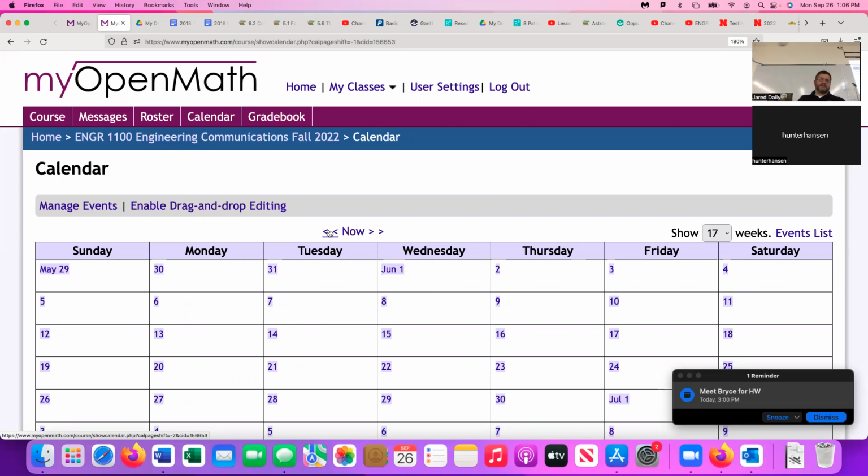That's a little too specific, because the pattern that you use to lay out your rebar is going to be determined by design things that you haven't done yet. You have to first design the bridge before you decide on a pattern to lay out your rebar in. You also wouldn't necessarily put in laying or surfacing the bridge with asphalt, because you may not end up surfacing with asphalt in your design. In the process of designing the bridge, you may decide that concrete is better than asphalt, and so you don't want to make any design decisions in your list of tasks.